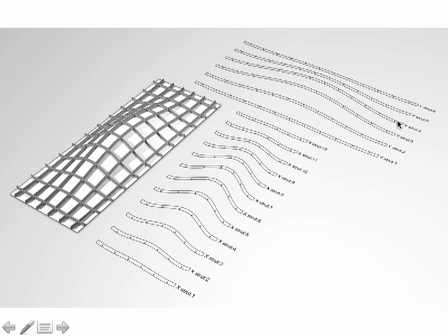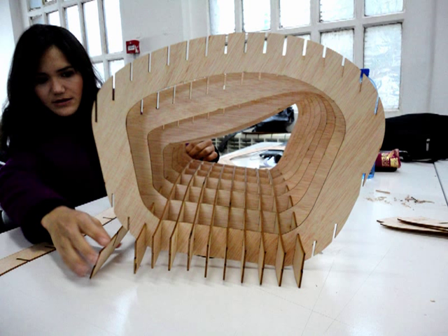Notice the labeling, the Y strut, X strut, so you can see that this person has already introduced that. This is a nice kind of plan for yourself too, to see what's what. And the process of assembly might look something like this. If it's not clear, you have ones that are cut in the top chord, ones that are cut in the bottom chord. You can cut them on any axis, depending upon your form. You might cut them in the X one way and the X the other way, so they fit together this way. Okay, it doesn't have to be this way.